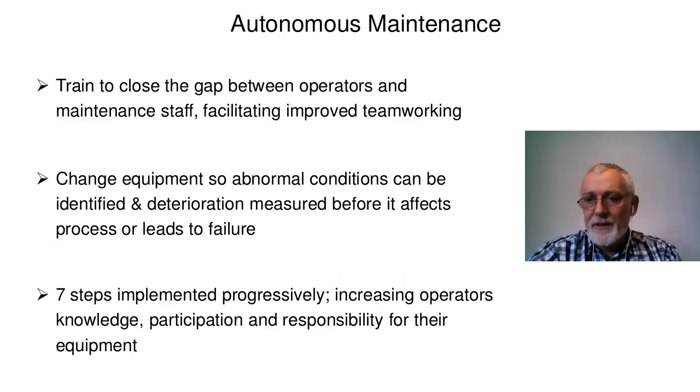one of the years when I worked in a foundry operation, we had operators who stopped a line one morning because one of the press operators noticed that there was a whine on the pulley at the top of the press that hadn't been there yesterday. We went in on a break and we did a quick inspection and discovered right up the top of the press that one of the major belts that drives the press was beginning to come apart. A couple of the clips that were holding it had come loose. And effectively we planned a maintenance intervention that evening.